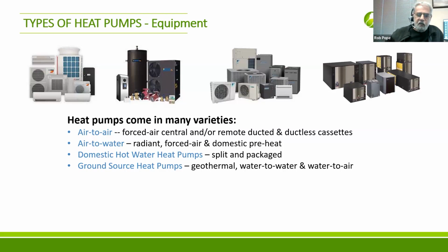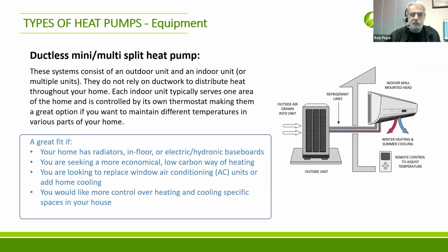And then ground source heat pumps. Geothermal systems are what they're referred to. They're water to water or water to air. So they're taking a liquid that you're piping through the ground inside pipes and transferring the heat from that liquid that it captured from the ground instead of the air and delivering it either to water, as in an air to water heat pump, or to air, as in an air to air. But today we're going to focus on the air to air systems. And by the way, if you have any questions or comments, please feel free to just jump in.